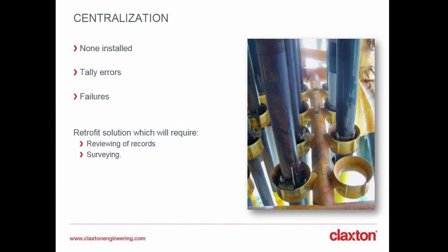Right, when it comes to centralization, a common problem that we've seen, in particular on some of the older platforms, is that perhaps centralization was not considered at all at the beginning, so there are no centralizers installed. It could also be that the previously installed centralizers have fallen down or slipped, so there's no centralization within the guide and the conductors anymore.